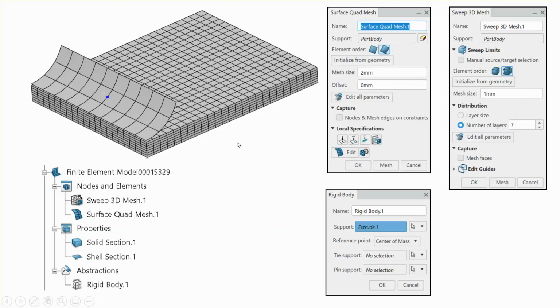And now, when it comes to defining the rigid body, well, first of all, we need a handler point. So instead of creating a point and selecting it, I said, okay, do it at the center of mass of that piece that I'm taking, which is incidentally that portion of the cylinder, which is this dot that you see there, and use the center of mass of it.